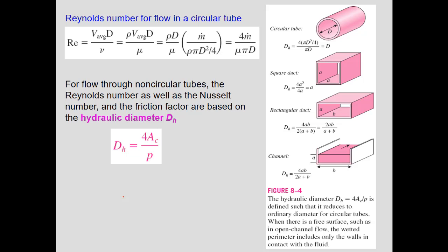So how can we calculate Reynolds number in a circular tube? We had Reynolds number. Please do not again mix this Reynolds number with the Reynolds number we calculated when we had external flow. The appearance is the same, but it is different. For the external flow, it was a ball or a sphere or a cylinder, and the flow was around that. But here the flow is inside something, inside the tube, inside the duct. So only the appearance is the same. D is completely different here.